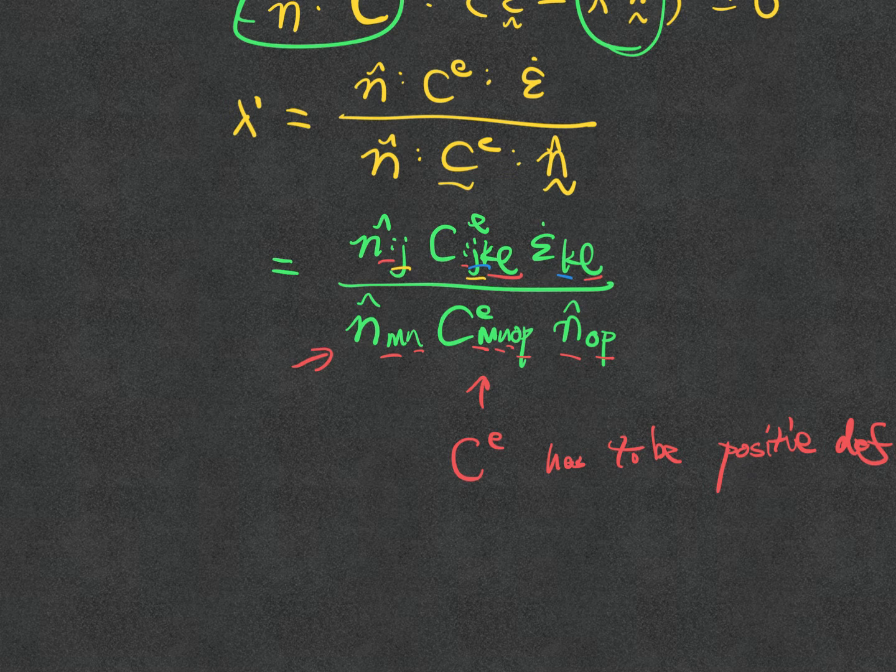Okay, so in general, when you write an elasticity model, you always assume C^e is positive definite, unless you know what you're doing. For example, if I want to model seams, then I may purposely have some potential value or some feature that gives me the bifurcation or unstable mode. But in general, I would write a stable model so that the Hessian matrix, which in this linear case is constant, is always positive definite. It's just to make sure that the model is stable.